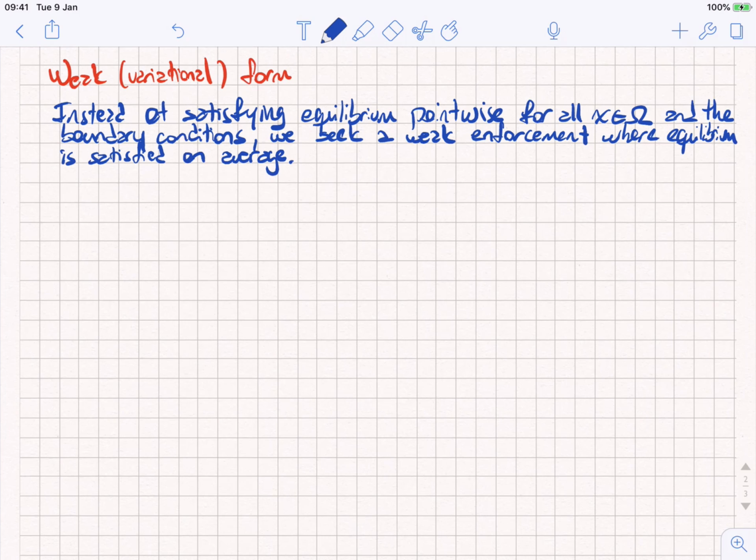and it's very simple. What we do with this method is we just take our differential equation, we multiply that by a function, right? In fact, as we will see in a few minutes, it's actually a projection that we do. We're projecting the equation in a space. We're going to get there. So we're taking our differential equation, we multiply that by a function, and we integrate over the entire domain, and we set that equal to 0. And then we're going to work from there to see what our weak or variational form of equilibrium looks like.